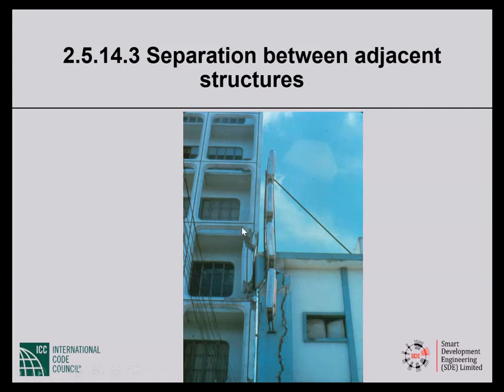So this is a building, this is an adjacent building. The floors are obviously not aligned. The floor is here, the floor is here, with the result that the heavy floor is hammering against the column of the neighboring building. And that is a very bad situation. In this case, there is very major damage.